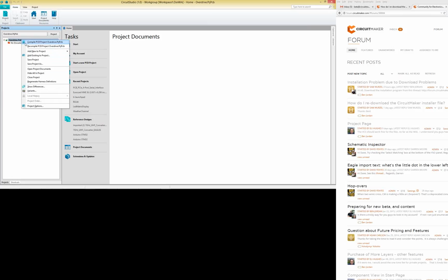I have this saying that I used to always train people in Altium Designer, and it's no different for CircuitStudio: if in doubt, right-click. We very much built the tool around the ability to use every part of the mouse. So there are right-click context menus for just about every single thing in this tool.